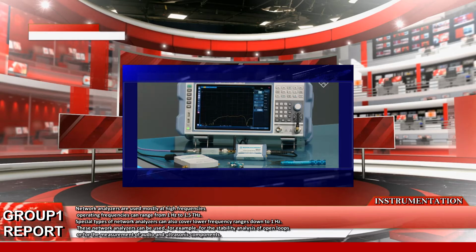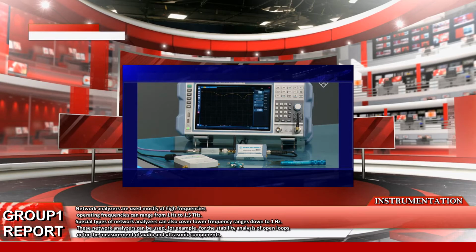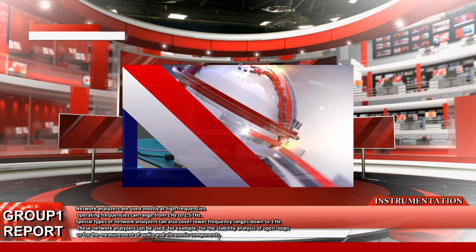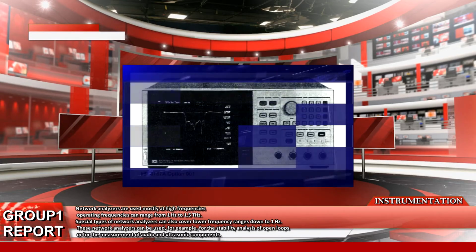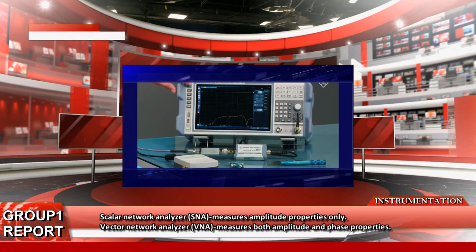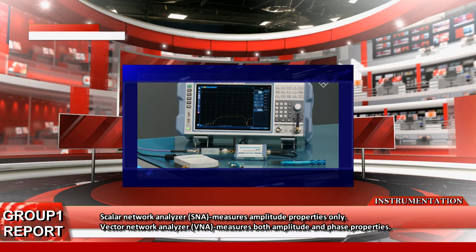These network analyzers can be used, for example, for the stability analysis of open loops or for the measurement of audio and ultrasonic components. The two basic types of network analyzers are the scalar network analyzer, or SNA, which measures the amplitude properties only, and the vector network analyzer, or the VNA, which measures the amplitude and the phase properties.